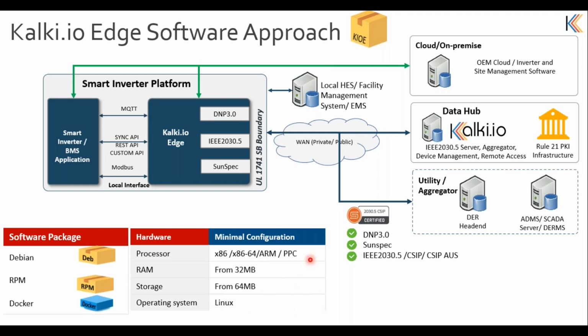You can have this cross-compiled and imported into your device, meeting any of these requirements. And it can be packaged as a DEB package, RPM package, or could be a Docker package as well. So there are various options we can work out depending upon the end device or the inverter platform capability. So this is all about the software-based approach for the 1547 compliance or 1741 SB compliance.